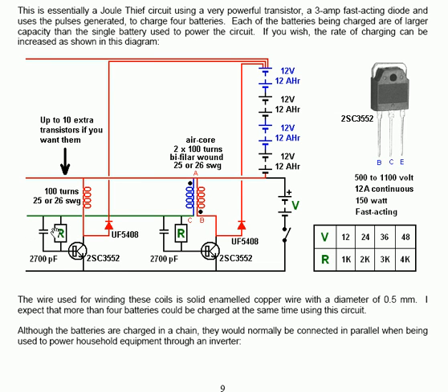The second one also feeds its plus through a separate wire to the plus of the batteries, and each of the additional stages has a separate wire going to the plus of the batteries. You may say, oh well, you could just connect the wires together. Well, yes, you could, but it won't work as well. Those separate wires are important for a multiple charging stage like this.